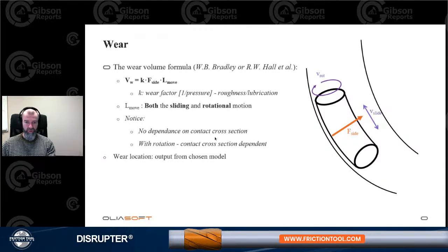But even though it now has a bigger contact area because there is a groove there compared to the first run of a drill pipe, you're still wearing out the same volume. But obviously we're talking about a volume, right? We're not yet talking about how deep the groove actually is.